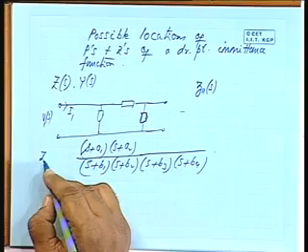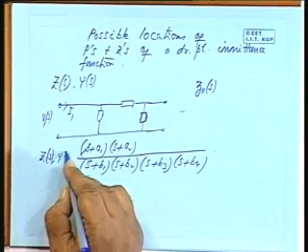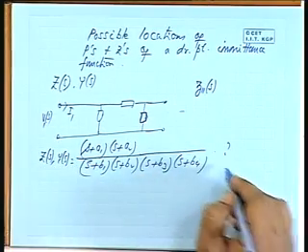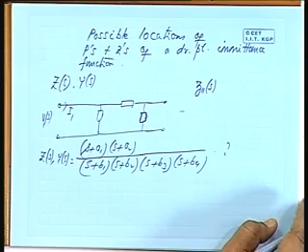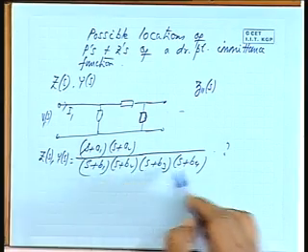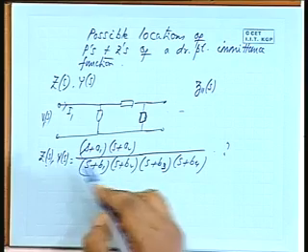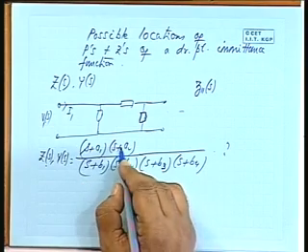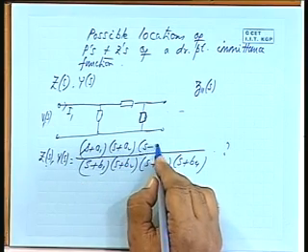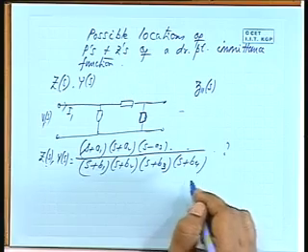Can it be a driving point impedance or an admittance? Is this possible? Any function of this type, can it be a driving point impedance or admittance function? Or is there any scope for a negative term, say (s - a3)? We would like to examine that.